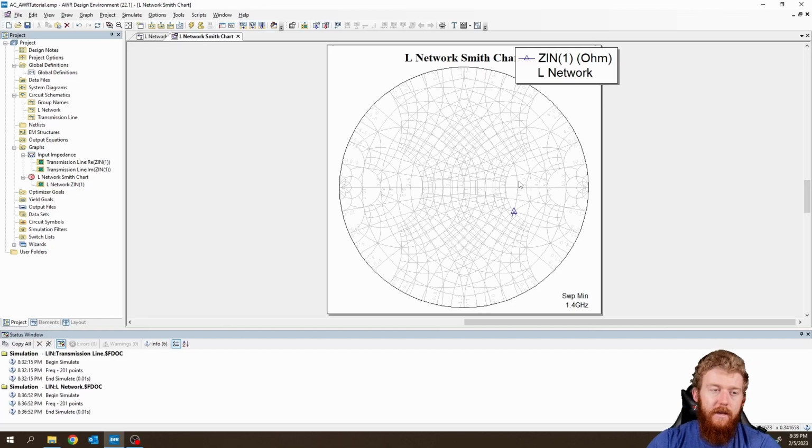That means the conductance is going to stay constant, and we are going to be modifying the complex part of the admittance here. So we're going to be adding things in parallel. We're going to start off with a parallel lumped component, and then we're going to end with a series lumped component. If you're familiar with L network matching, you know that you're going to need one series, one parallel typically, but there are all sorts of different ones.